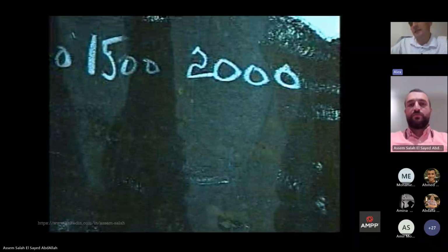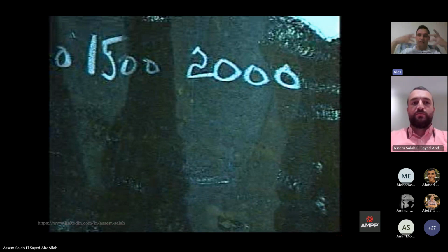Yes, right. I mean, yeah, this is called osmosis, when the salt attracts water from the seawater. If you have salts on the surface of, for example, a metal structure which is underwater, in a ballast tank or the hull of a ship, it will attract the water which is in seawater. The water will penetrate through the barrier of the film coating, and it will make a bubble which is subject to blow and destroy the barrier protection of the film coating.